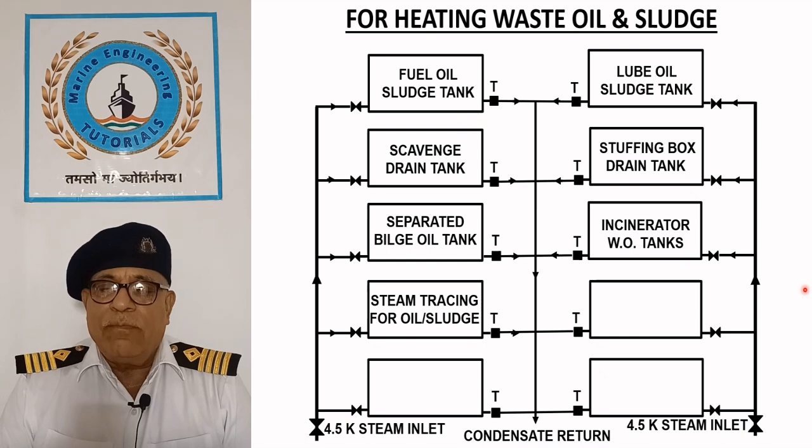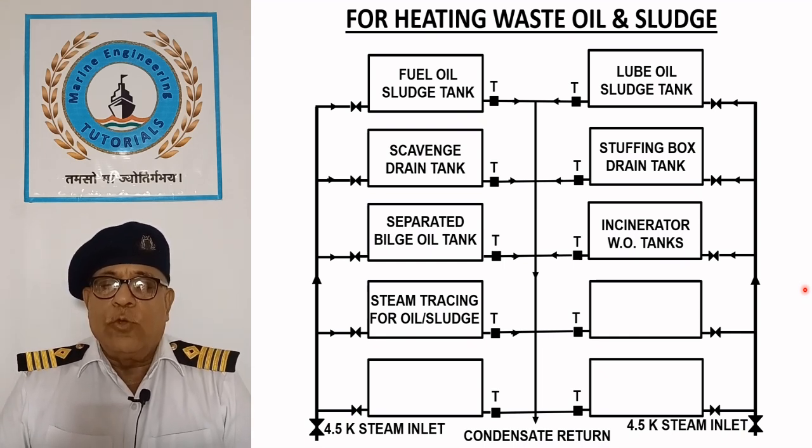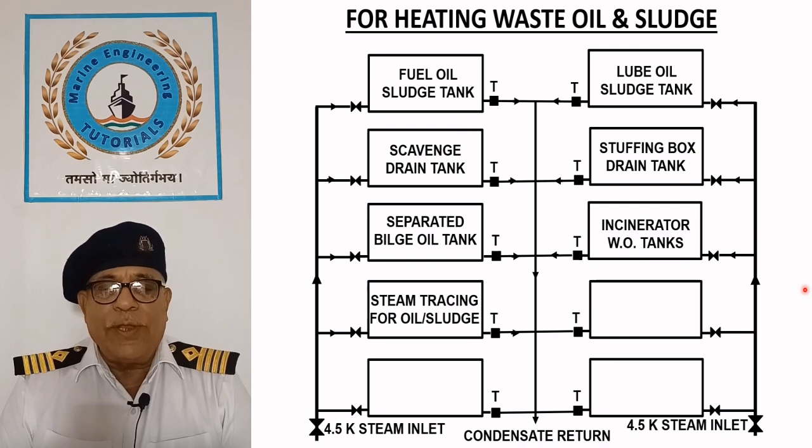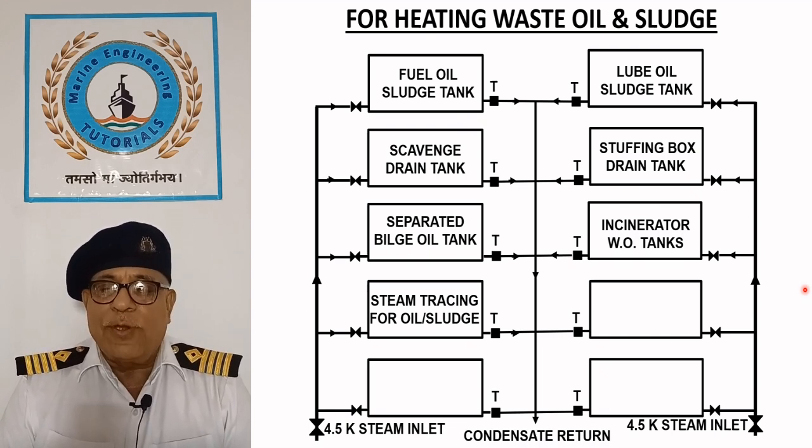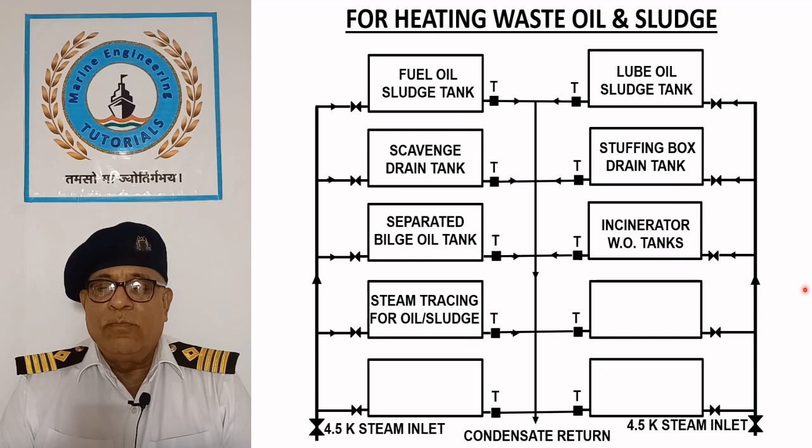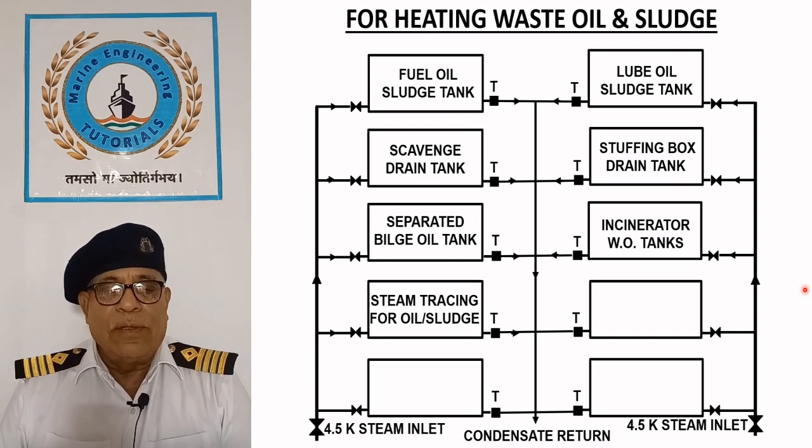The temperature of heavy fuel oil and sludge oil during transfer is maintained using a small diameter steam tube that runs along the main pipe. This method is known as steam tracing.